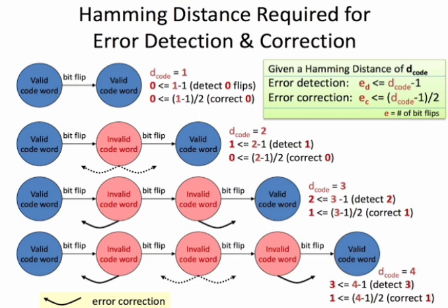Linear block codes: b_0, b_1, and so on up to b_(n minus k minus 1) are the (n minus k) parity bits. m_0, m_1, and so on up to m_(k minus 1) are the k message bits. Any model can be used. Structure of the code word of a block code: G equals [I_k : P], a k by n matrix, equal to the generator matrix.